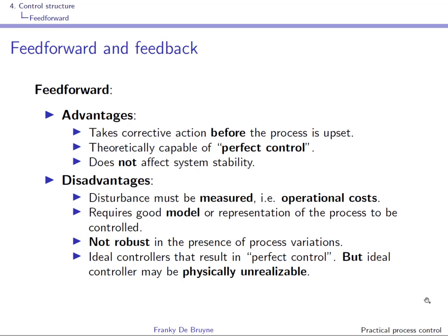The advantage of feedforward is that the corrective action is taken before the process is upset, so before you see the influence of the disturbance on PV. And in theory, perfect control is achievable. Unless you're really careless, right? Feedforward should not affect the system stability.